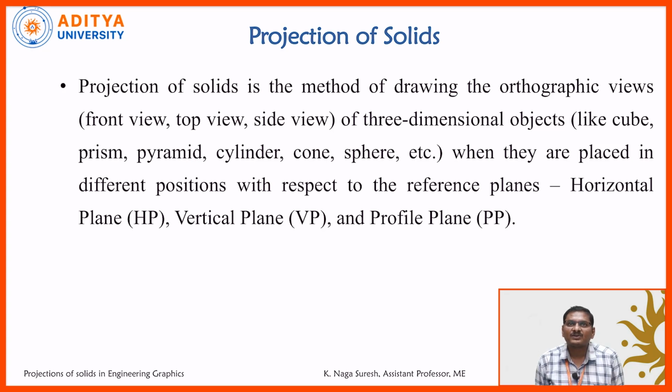First, what is the meaning of projections of solids? Projection of solids is the method of drawing the orthographic views, front view, top view, and side view, of three-dimensional objects like cube, prism, pyramid, cone, and sphere, when they are placed in different positions with respect to the reference planes like the horizontal plane HP, vertical plane VP, and profile plane PP.